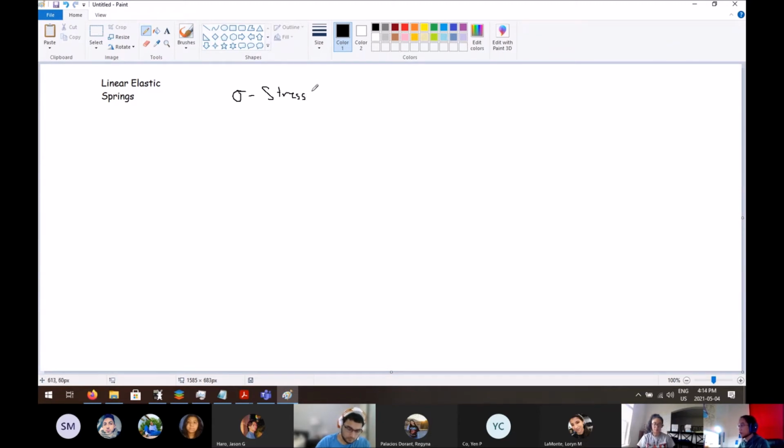And this is measured in the units of KSI, so kips per square inch, a force over an area, right? No, that is an axial force. Remember when we did internal reactions? P was axial, V was shear, and M was moment.